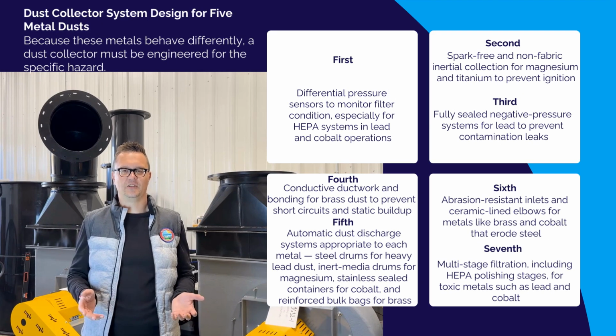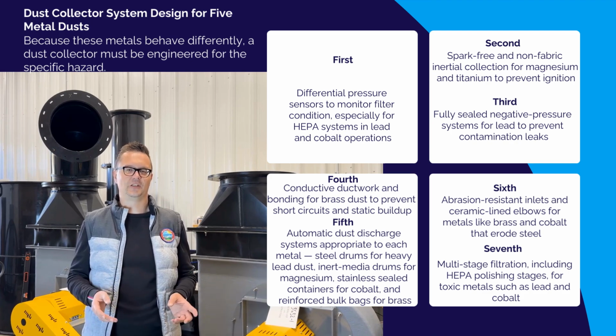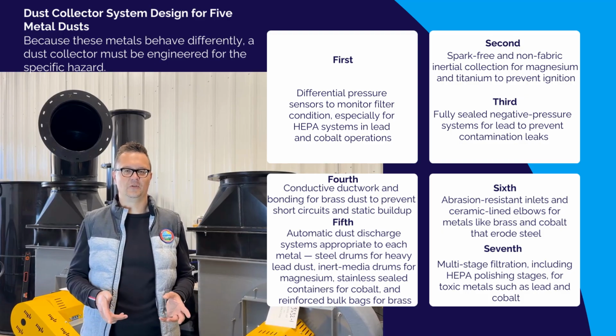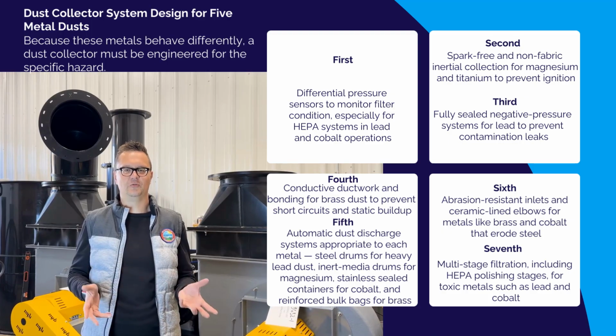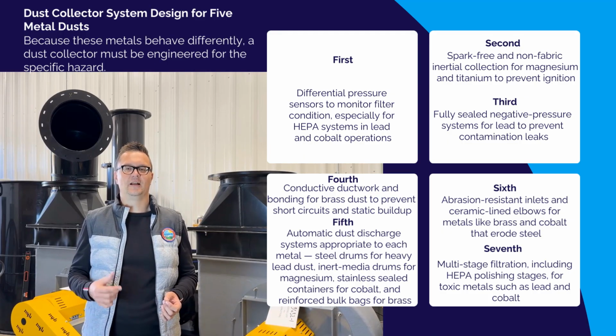Dust collector system designed for 5 metal dusts. Because these metals behave differently, a dust collector must be engineered for the specific hazard. I design, first, differential pressure sensors to monitor filter condition, especially for HEPA systems in lead and cobalt operations. Second, spark-free and non-fabric inertial collection for magnesium and titanium to prevent ignition. Third, fully sealed negative pressure systems for lead to prevent contamination leaks. Fourth, conductive ductwork and bonding for brass dust to prevent short circuits and static buildup.